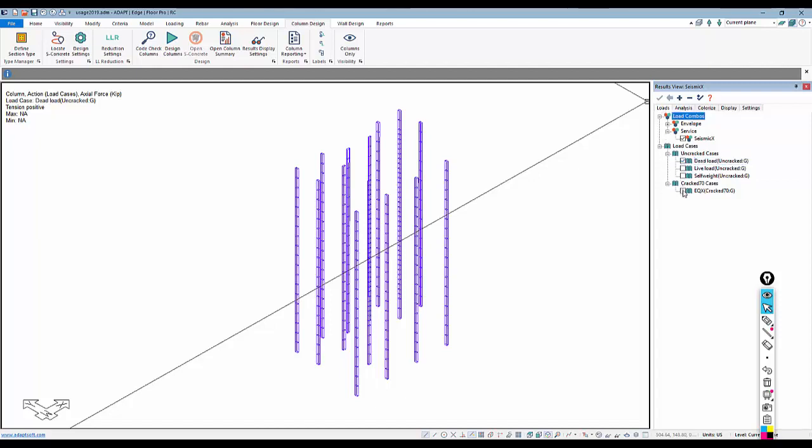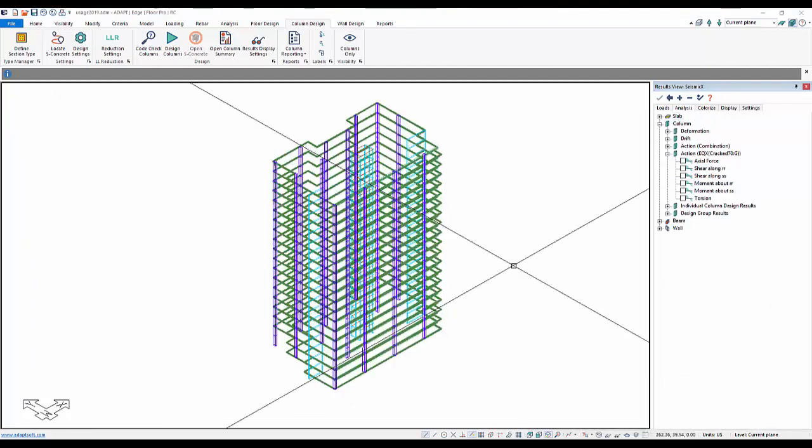If I select EQX70, now that the analysis is done, it's important to note that the program stores only one global solution in its entirety at the time that it's run. So if I run cracked 70, that's the latest solution globally.